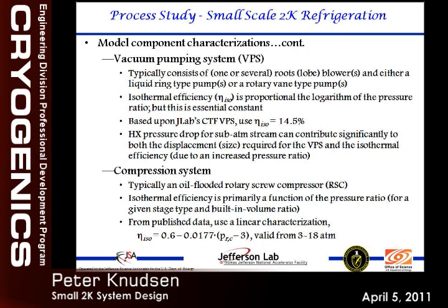So, continuing with the component characterizations for the vacuum pumping system. We're assuming for this study 14.5% for the isothermal efficiency. That's based upon data that we gathered from our CTF vacuum pumping system. And the compression system typically is going to be a rotary screw compressor, and we have good data on that.